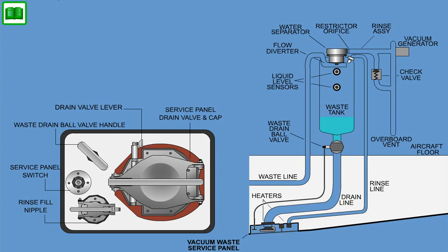Mechanical stop devices on the service panel door will not permit the door to be closed if either of the valves is open or if the drain cable is not fully seated. One stop device enables operation of the system by closing the service panel door switch contact.